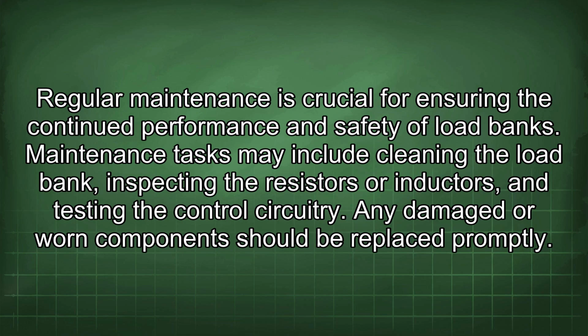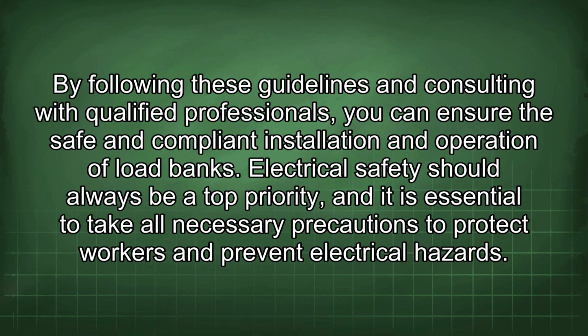Regular maintenance is crucial for ensuring the continued performance and safety of load banks. Maintenance tasks may include cleaning the load bank, inspecting the resistors or inductors, and testing the control circuitry. Any damaged or worn components should be replaced promptly. By following these guidelines and consulting with qualified professionals, you can ensure the safe and compliant installation and operation of load banks. Electrical safety should always be a top priority, and it is essential to take all necessary precautions to protect workers and prevent electrical hazards.